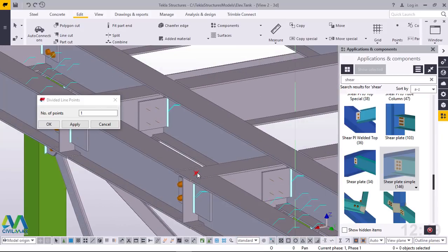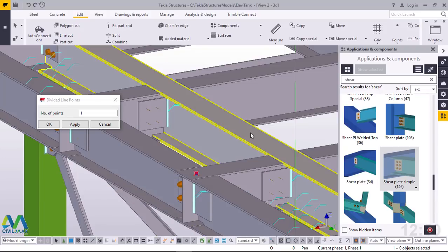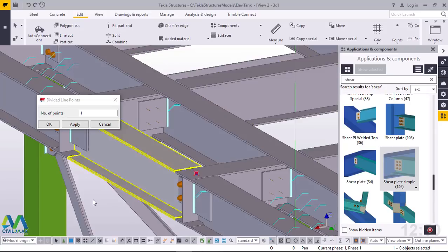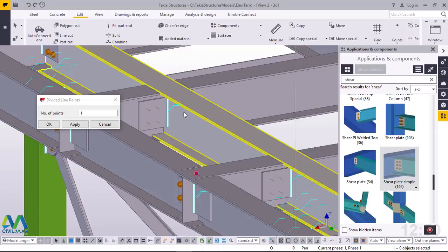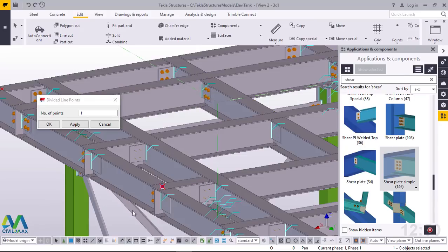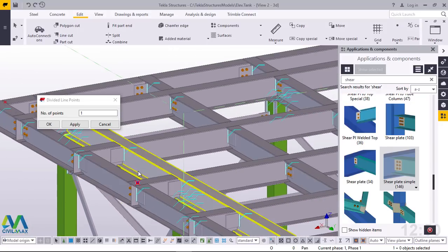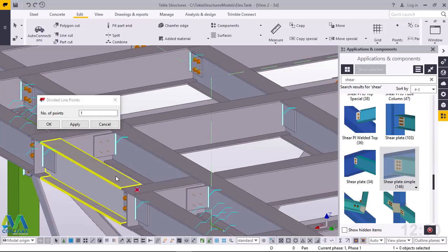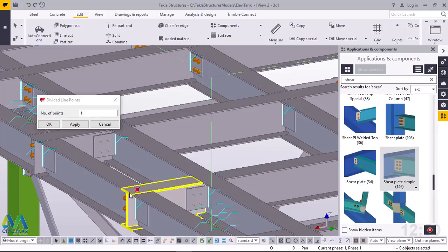Now I want to offset this point, the other end by 350 and this end by 350. This will be the access to our platform all the way from the cage ladder. The cage ladder will be coming all the way from 0 point or 0 level all the way to the platform, and this will be the access point or the entry point to the platform. Now I want to offset this by 350 so that our space will be 700.